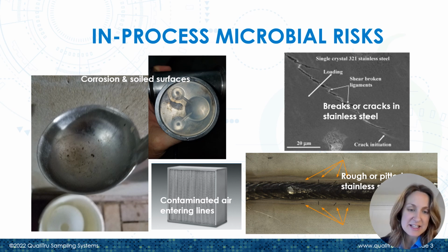The ladle here has just been dropped enough times that you get cracks in there. The pictures here on the right show some cracks and pinholes. As stainless steel heats up and cools down, with time you'll see that the stainless steel will open up and then close. And so here's an example of a crack in stainless that allows bacteria to go in.